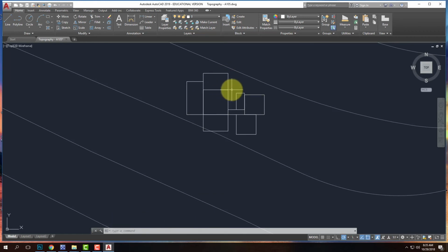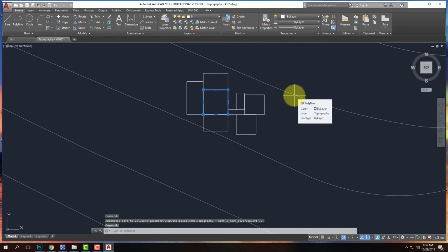Those are the kinds of things that you want to think through as you're creating this floor plan, not just, I satisfied the square footage requirements. Think about the dimensions of your spaces. So for example, the living room. The first one that I did was 10 feet by 20 feet. It's really long and skinny.